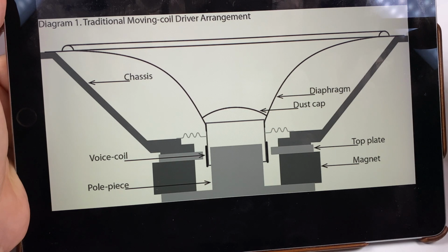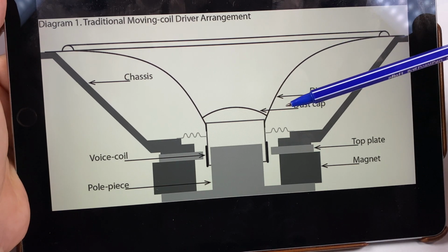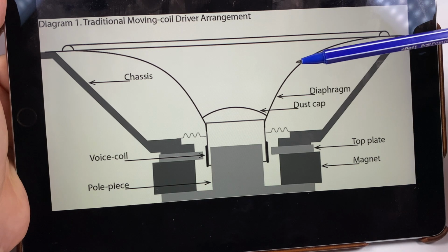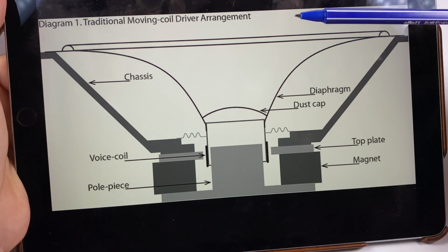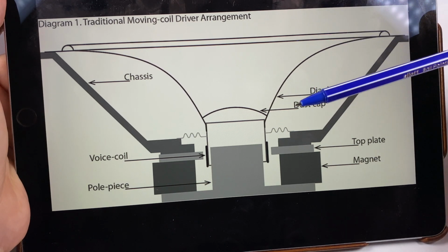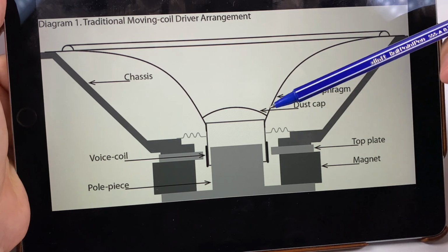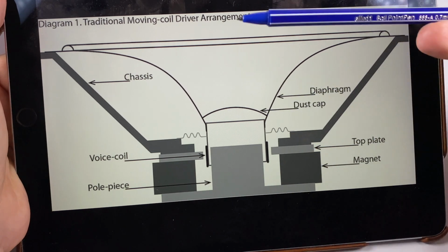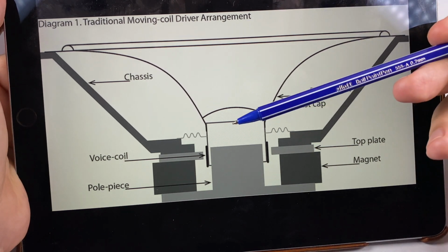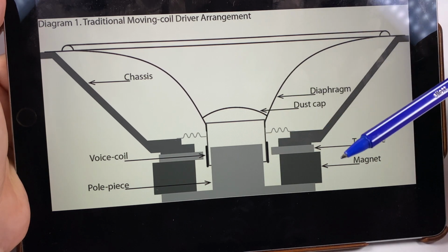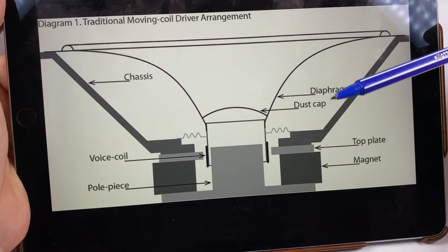We are pretty successful nowadays, not we, the manufacturers of speakers are pretty successful nowadays, and there are a lot of good solutions, but they are expensive, and anyway the diaphragm is heavy and it still can't move as fast as, for example, balanced armature speakers. So the resolution of dynamic drivers is a bit lower than other driver types, but anyway it's usually enough to produce good high quality sound, of course.